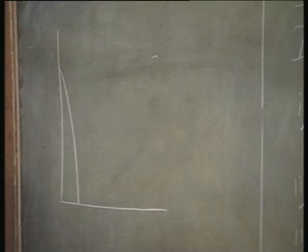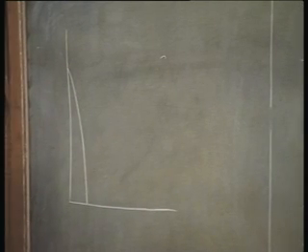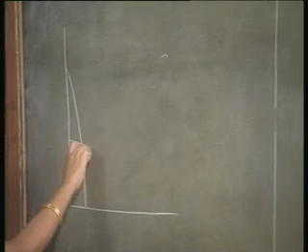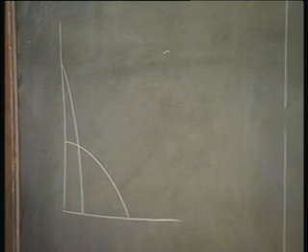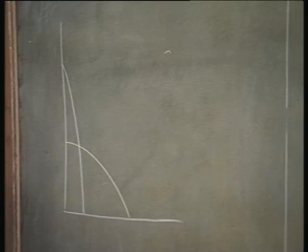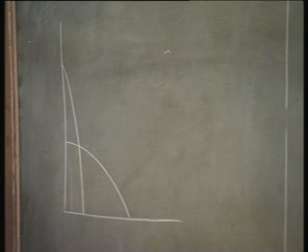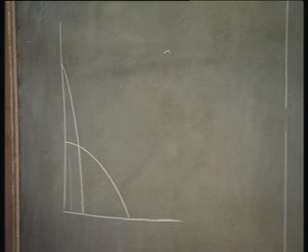This is a complementary error function profile. I have a high surface concentration and a shallow junction. And if I want to reduce this surface concentration, I have a low surface concentration but a deep junction. But how do I get a low surface concentration and a shallow junction? This is going to be quite difficult for a diffused system, isn't it?